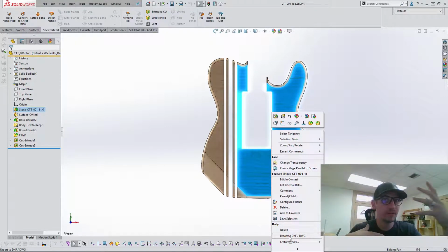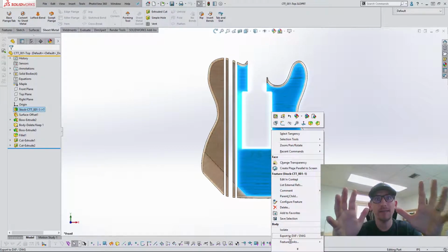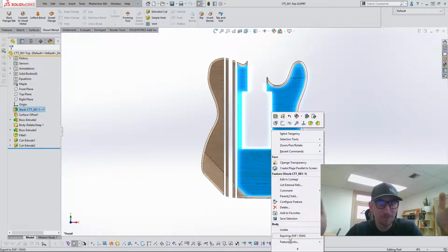As I've done in some other tech tip videos in Just a Thought Thursdays, there might be applications where you export out as a DXF DWG using the save as function, and SOLIDWORKS crashes on you. It happens. It actually happened to me earlier today. And so you might find that SOLIDWORKS is more stable when you right click on a face and export that out.